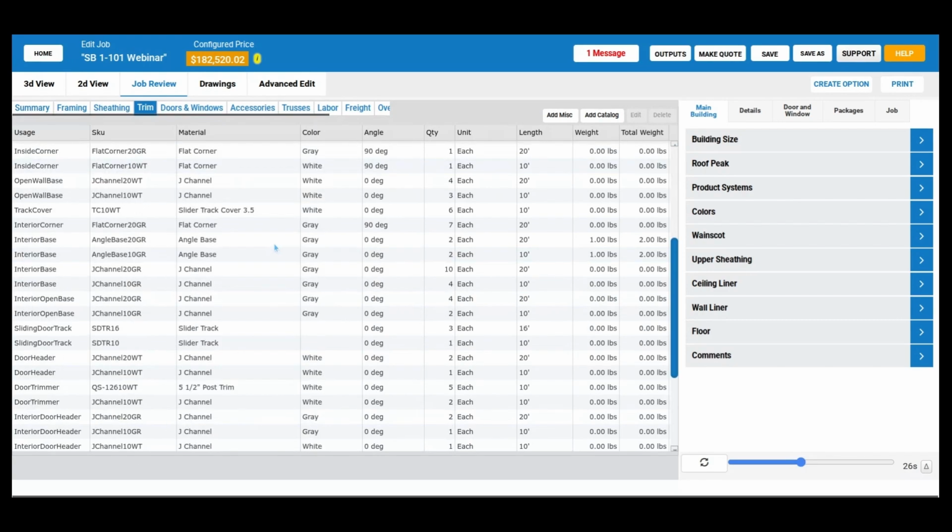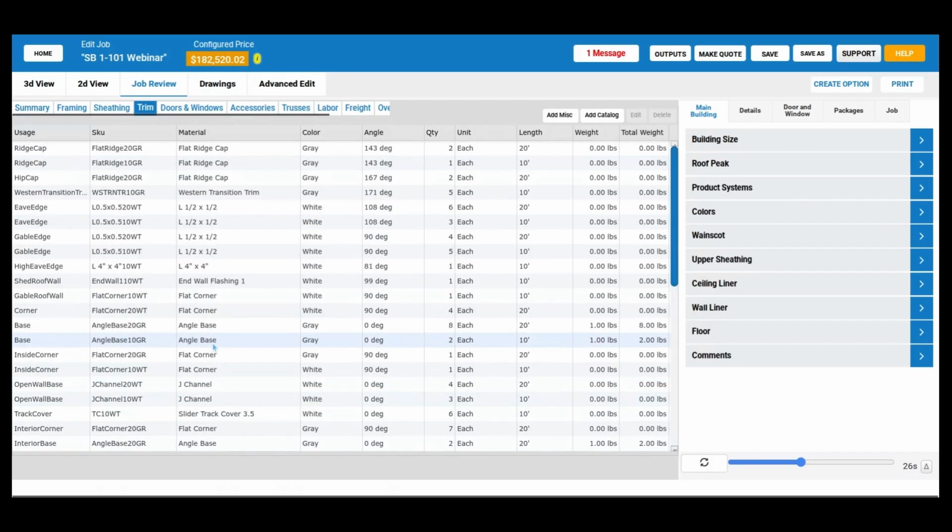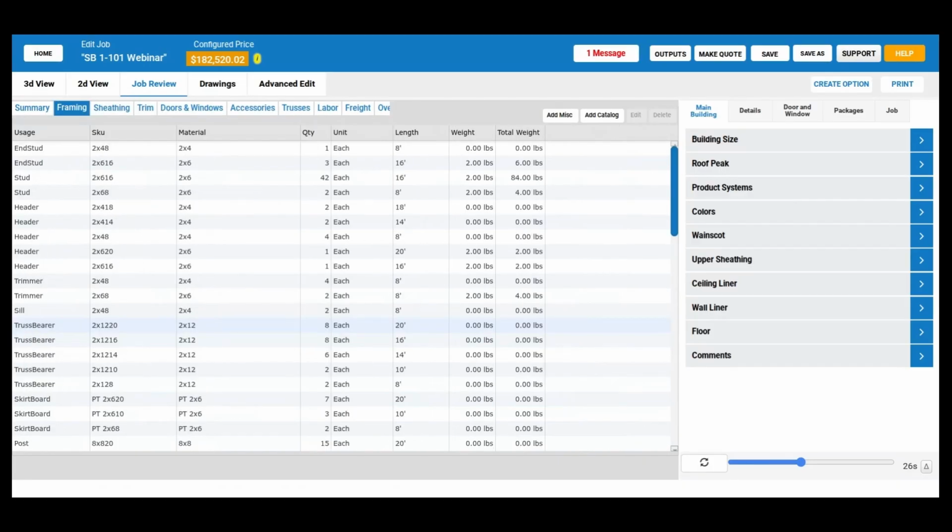So at this point now, if it's interior, whether it's matching the exterior or matching the liner, it is going to show up underneath these interior categories. Except for the stud framing, which, well, that's one of those things that if you do want to see that, let us know. Right now, we're just keeping all the stud framing in a single group. So studs are just going to come in as studs, and you can decide where you want to put those, but they're not going to be separated out by interior or exterior if you're doing exterior walls as stud frame as well.